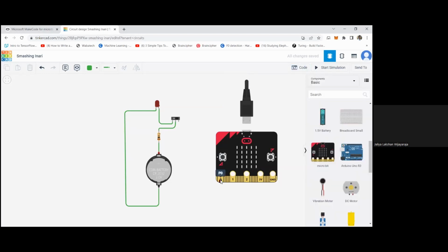Now, at the very beginning of the microbit session, I introduced you to the several pins in the microbit device, which are 0, 1, 2, and there's a 3-volt pin and a ground pin. The 3-volt pin is actually a 3.3 volt pin, so it will emit 3.3 volts when we turn the device on, and the ground pin is always grounded.